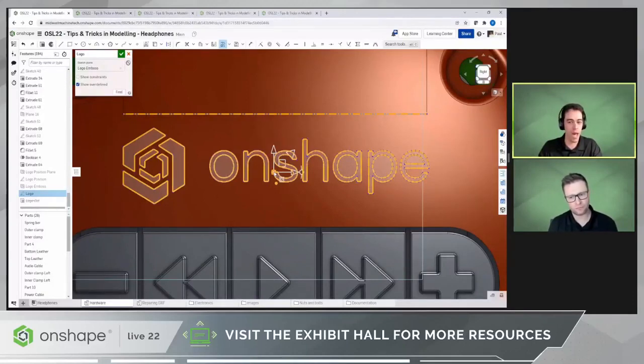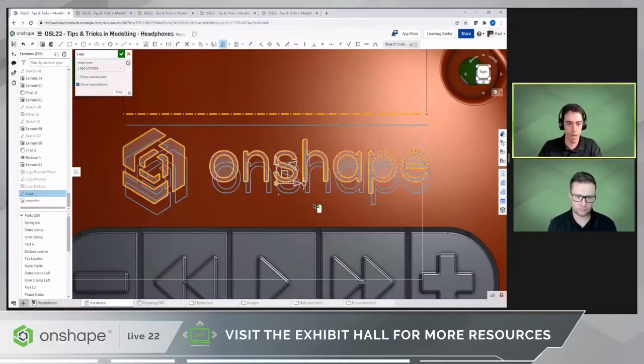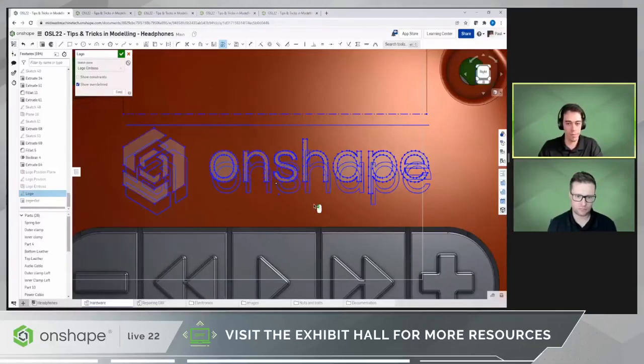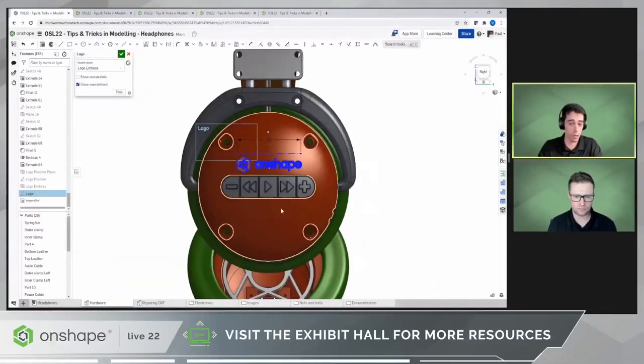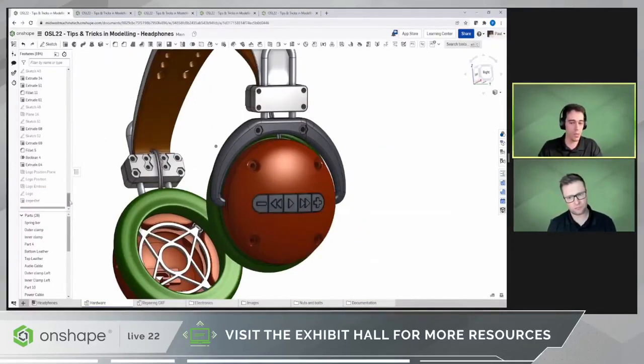And then you can drag the whole logo and snap this point to a specific location. For example, this point that I have right here. So let's do that. I can drag the logo until it snaps to my desired location. Now, with this logo, I could cut into the outer cut here, this red part that you can see here. So let's just confirm the sketch and cut the geometry, right? I've already created an extrusion for that, so I can just unspress to get my cut.